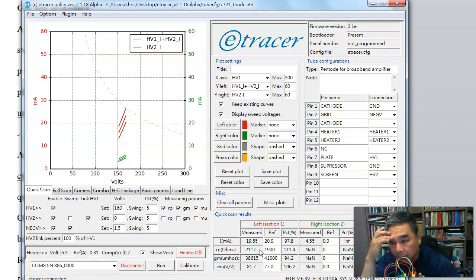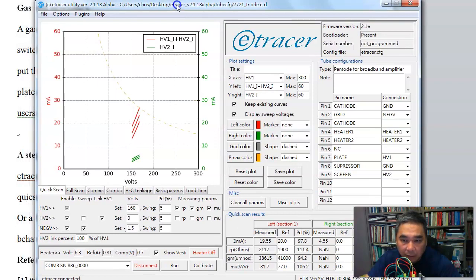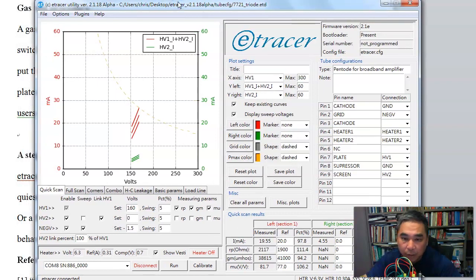This amount of increase reflects how gassy the tube is, according to the TV7 manual. So you can probably set a criterion, say if it's within 1% of the target in the reference manual, it should be okay, something like that. So basically this is a gas test done manually.